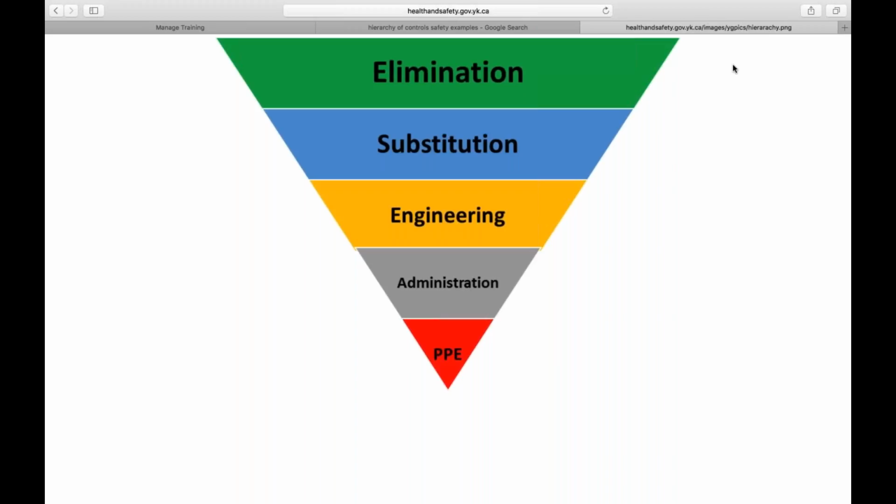Basically, that site safety plan has to be coordinated with other groups. Who does it have to be coordinated with? It has to be coordinated with the client, with general contractors, and maybe with other subcontractors and contractors that are going to be on the site. We need to make sure that we have clear direction before the job even starts. Before we start putting employees out there and allowing them to work and be at risk, we need to make sure that we have our health and safety plan done, and that we're working in conjunction with, like I said, the controlling entities, the general contractor or prime contractors, and other contractors as well.